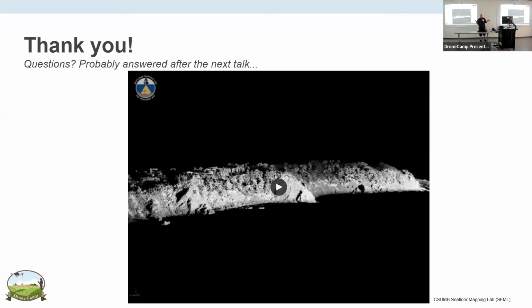But so yes, if you get a 3D point cloud from one source and a 3D point cloud from another source, and they're all accurately geo-referenced, you can merge them together. What we would do a lot of the time is a bathymetric survey at the highest possible tide. So we're shooting up into the intertidal zone, onto shore a little bit, and then come back at the lowest possible tide and do a terrestrial LiDAR survey. There's going to be a little bit of overlap between them, hopefully, and merging them is actually really easy. And you get seamless data from hilltop to Marine Canyon.